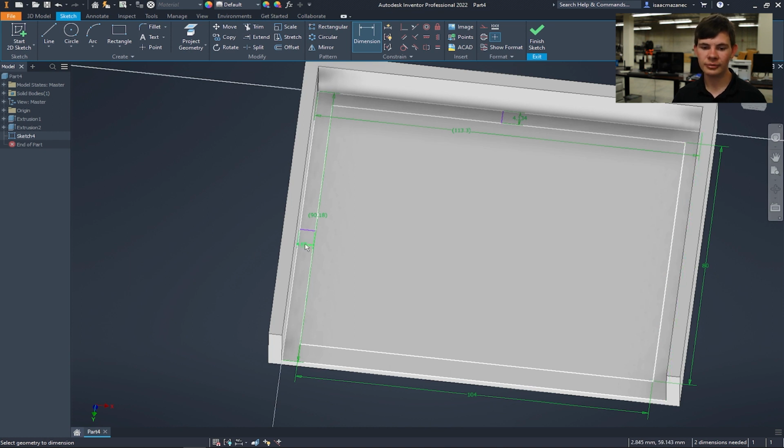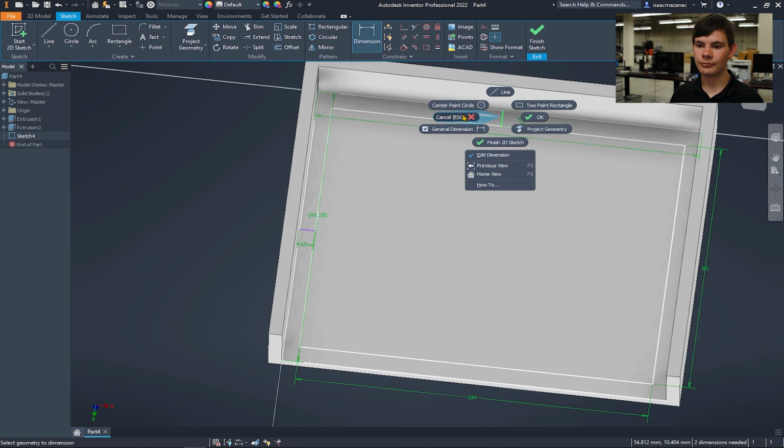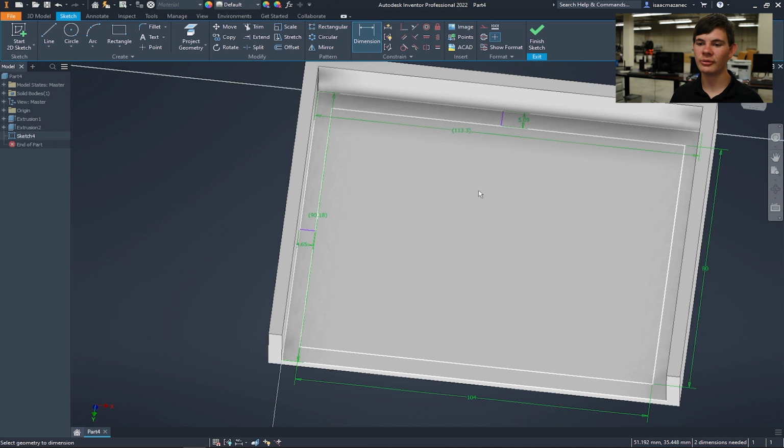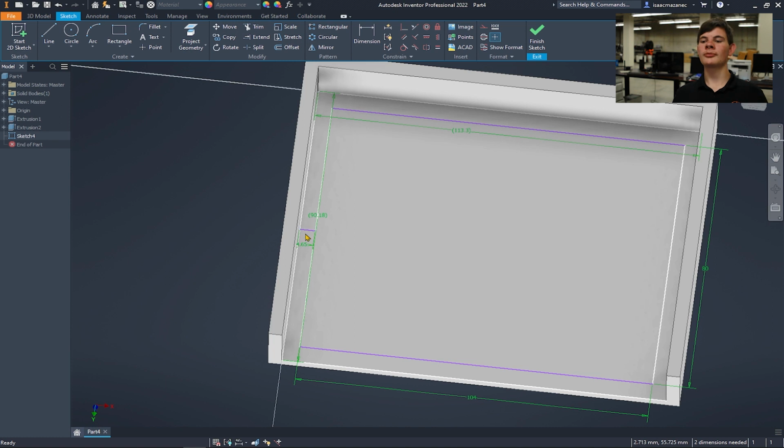So we can remove this, I'll do that later. And then here is the same thing. The whole distance here subtracted here to get the space here, divide by 2, which is 5.09. And now the space here is the same as the space here. So now that we're done with those lines, I hope we can delete. Just press the delete button. I have to get rid of the dimensions. Does that work? It does. Okay. So now we have this plane here, so we can add the circles.